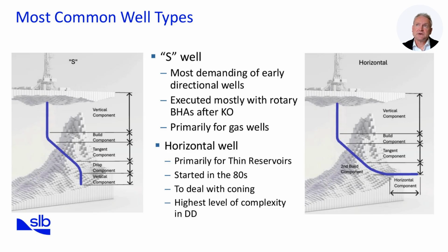This is because during the cementing phase, it is essential that the cement is not compromised by gas ingress while setting. Drilling vertically into the reservoir minimizes this risk. However, this is limited today due to gas-blocking additives that can be added to the cement to prevent gas ingress.